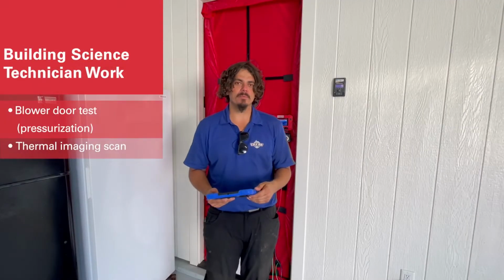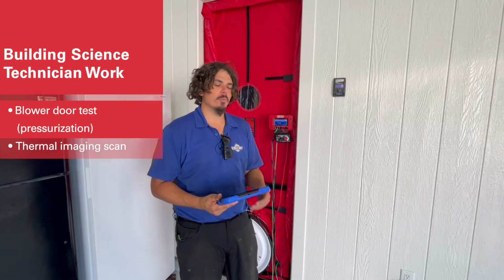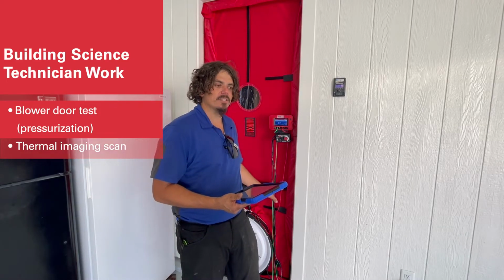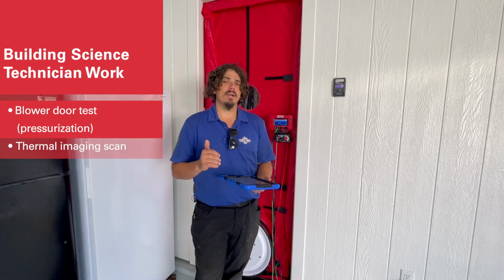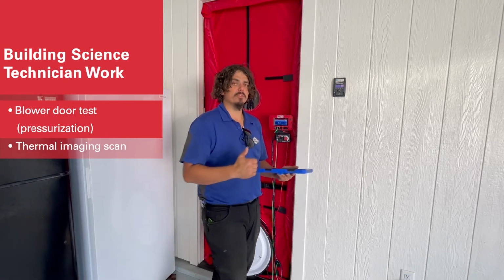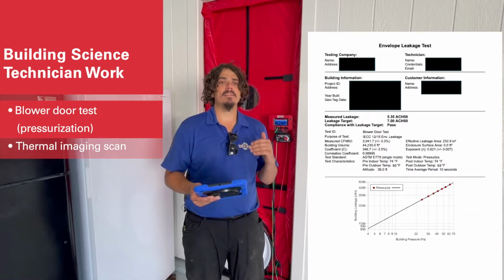Okay, we just finished up doing the blower door test. We chose pressurization in this case because earlier, through the walkthrough, we observed the presence of some microbial growths, and we did not want to bring that into the home, so we chose to pressurize and push that out of the house.